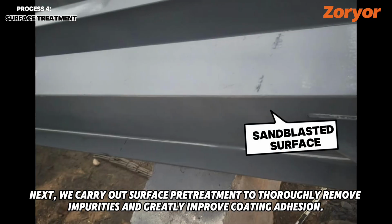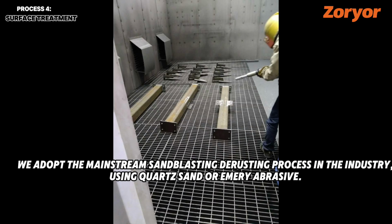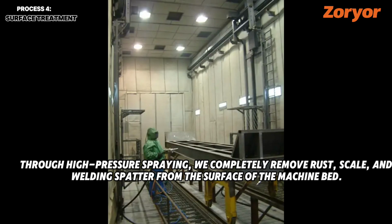Next, we carry out surface pretreatment to thoroughly remove impurities and greatly improve coating adhesion. We adopt the mainstream sandblasting derusting process in the industry, using quartz sand or emery abrasive. Through high-pressure spraying, we completely remove rust, scale, and welding spatter from the surface of the machine bed.